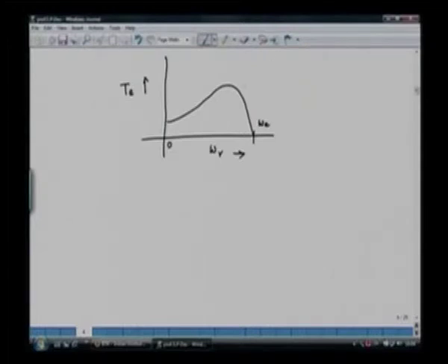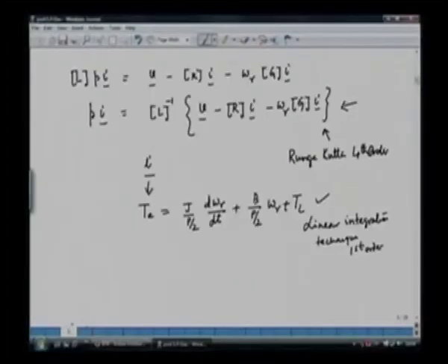This has been obtained by assuming steady state equivalent circuit. The equivalent circuit, which you have already studied in your previous courses in electric machines, especially in the undergraduate second year level, gives the torque speed characteristic of a steady state machine. The machine is in the steady state condition. But here when we are simulating, the machine is actually the actual machine. It is basically proceeding from the transient condition to the steady state condition.